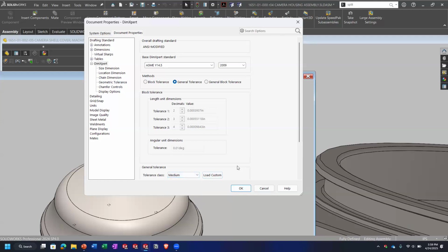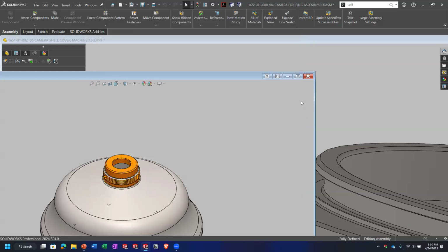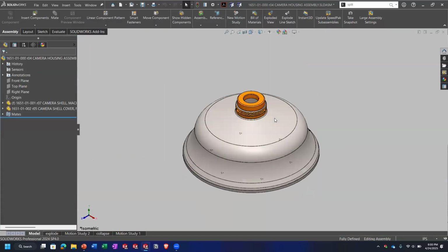You may choose to have a part template. Maybe you have 2 or 3 different templates like, oh, this is going to be a tight tolerance part, this is a medium tolerance part or something, just to get you in the right ballpark. You're going to do a sheet metal part versus a machined tight tolerance part. Maybe you have a couple of templates for that so that you have your predetermined tolerance blocks configured that way. Because nobody wants to hold their sheet metal to like plus or minus half a thou or something.